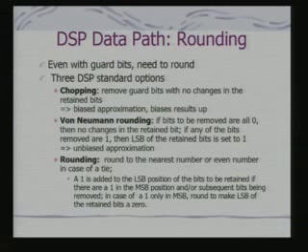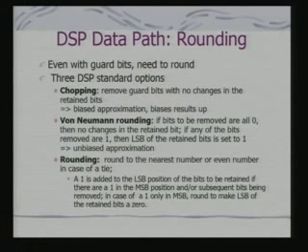What is the difference with the previous method? In the previous method, I just set it to 1. In this case, I add 1 to the LSB. And if the bits which I am removing, let us say 3 bits, are 1 0 0, then what do I do? I actually add 1 if the LSB is already 1, and otherwise I keep it 0. That means, what I am doing? I am trying to make the LSB always 0, that is an even number.